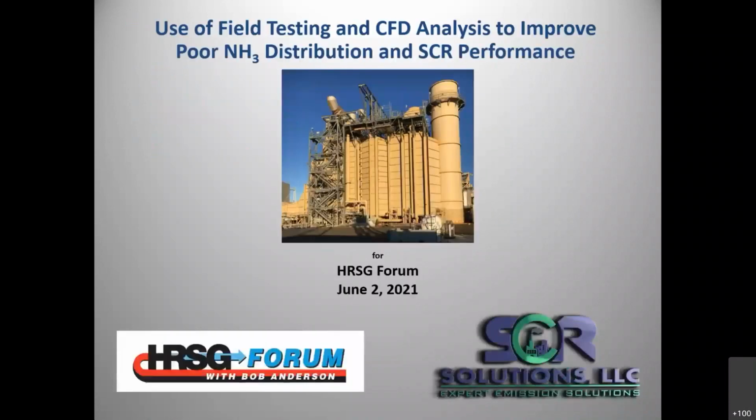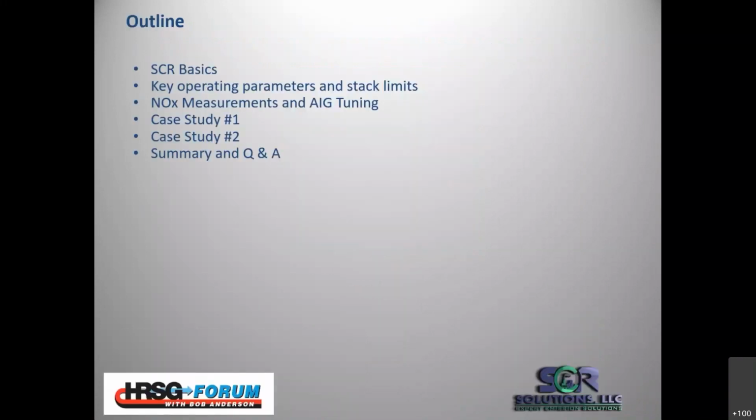My presentation here today is, it's a big long title, use of field testing and CFD analysis to improve poor ammonia distribution and SCR performance. So I'm going to have a little outline here, just cover some very basic SCR operation parameters and typical stack limits, and then talk about the types of NOx measurements and tuning that we do, and are pretty unique in how we go about this.